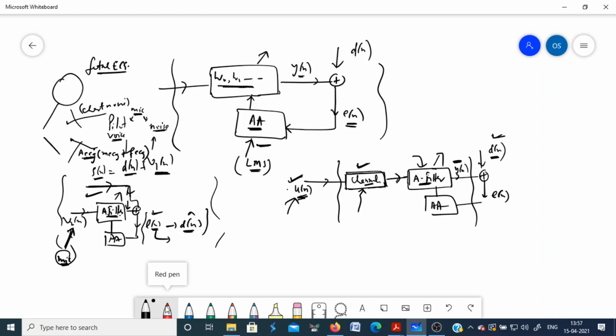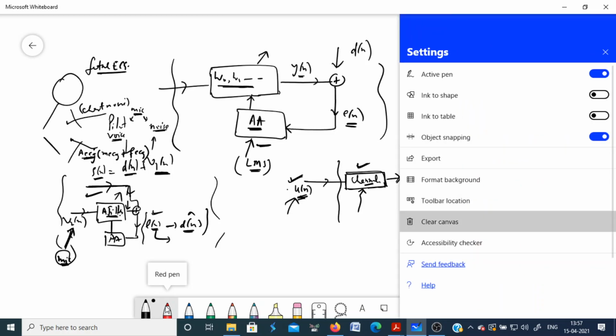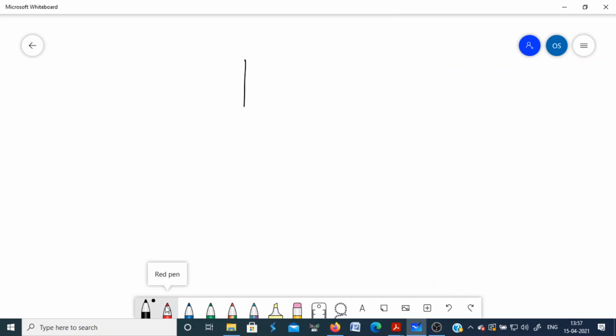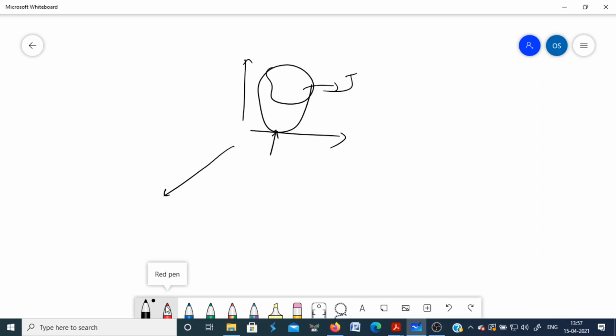To conclude, in the Wiener filter, on the error performance surface, your mean square error is an m-dimensional function of the filter weights w0, w1 and so on. That is a bowl type surface with a unique minimum, which we have obtained using the gradient operator, and which gives you the minimum value of the mean square error. The same can be achieved using adaptive filters.